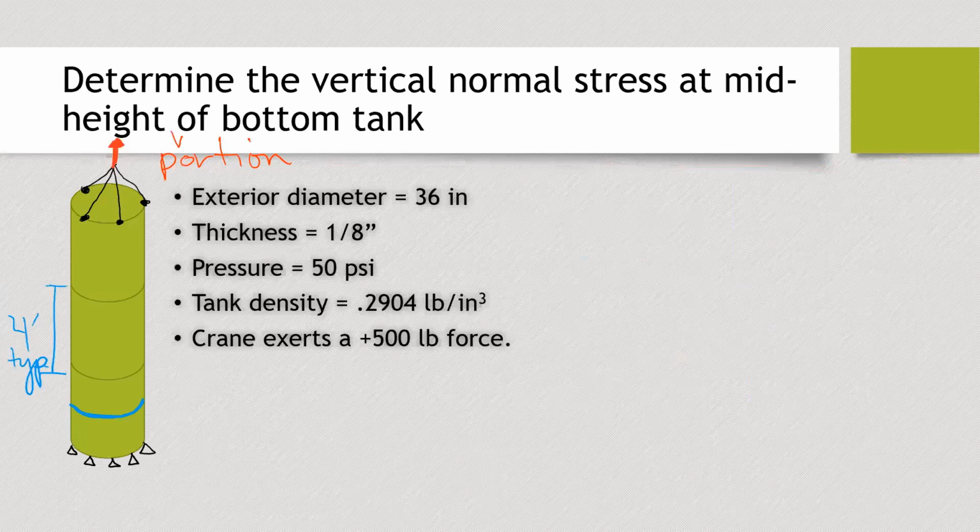So what do you want to attack first? Pressure? Okay, we'll get the pressure vessel part out of the way. We know that we're concerned about the vertical direction. So in this case, is that my hoop stress or our longitudinal stress? Okay, I heard longitudinal. So that's PR over T or over 2T?